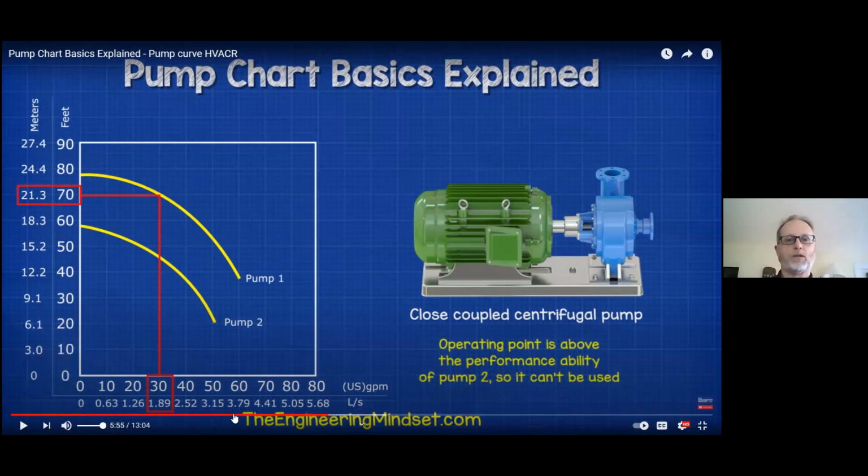They know, typically in gallons per minute or liters per second, how much flow we need to suit that application. We know from elevation how many meters of head we need, and they would build into this head calculation things like the pipe diameter and material, and they have formulas to calculate that. And they're just plotted out on the graph.